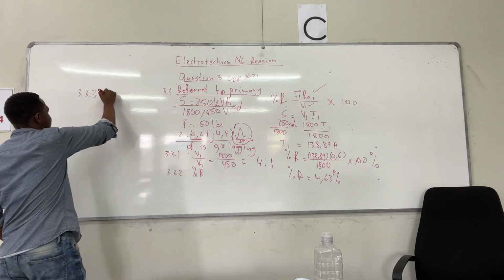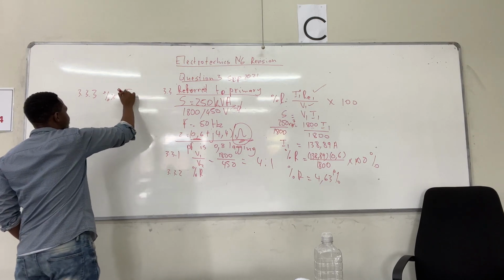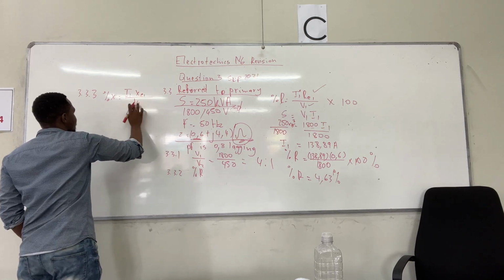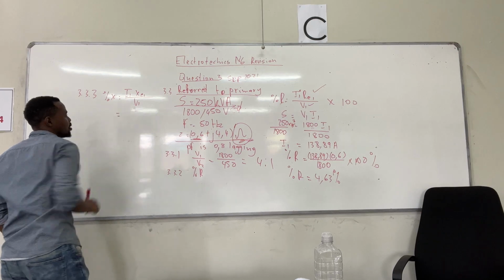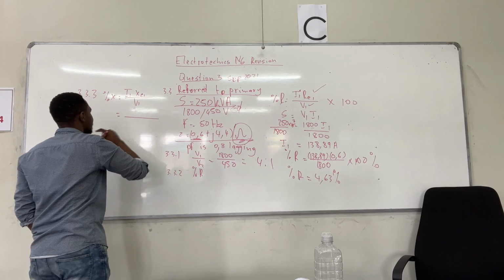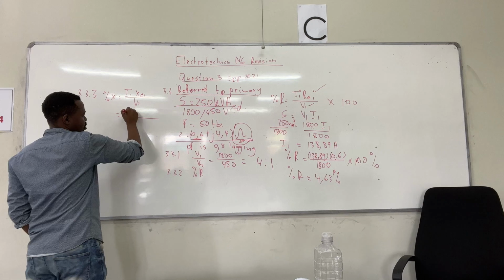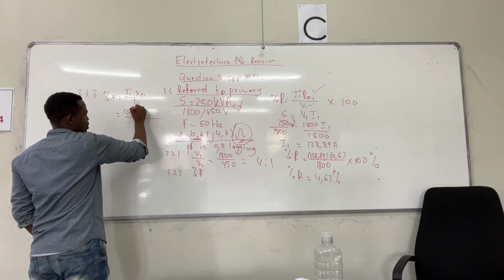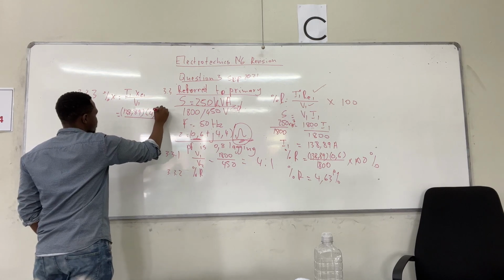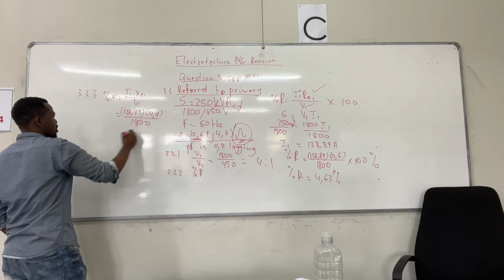So the percentage reactance would be I1 X_E1 over V1, which is 4.4 over 1800 times 100.